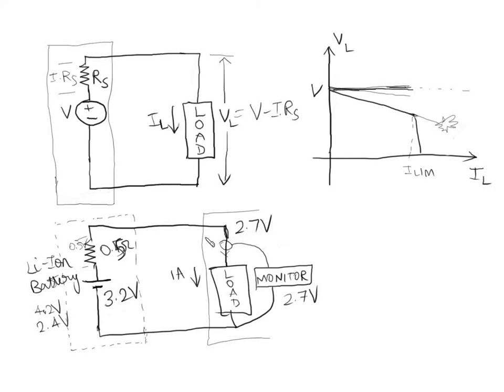The phone will just turn off. So this is how over the years you will see a reduction in the total runtime you get from your battery, because as it ages, the intrinsic resistance of the source increases, and so the voltage actually delivered by the battery continuously reduces for a given amount of current.